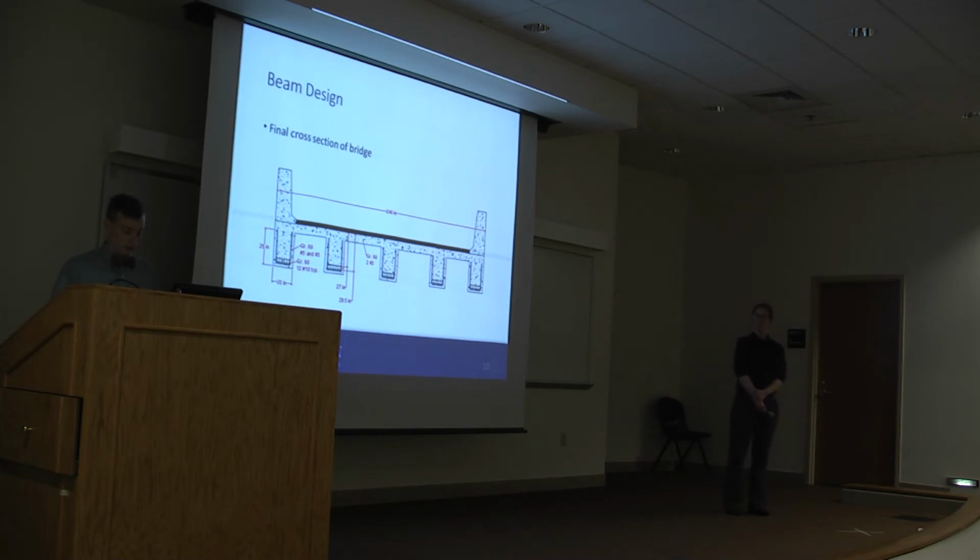The beams turned out to be 26 by 20 inches through an iterative process using spreadsheets. We had 12 number 10s at the bottom in 2 layers, 6 each layer. Also, we had 2 different shear reinforcing, number 5 and number 3.